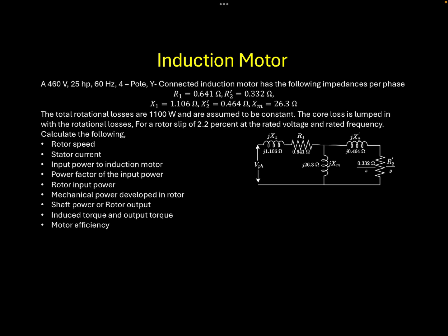the first reactance and resistance elements correspond to the stator equivalent circuit. Now, the current that is entering this particular circuit is nothing but your stator current. And if you use the value of the input voltage, that is V phase, and Is, then we will get the value of input power that is given to the induction motor. Now the power factor of this particular power, or the phase angle difference between this voltage and current, will give you the power factor of the input power.